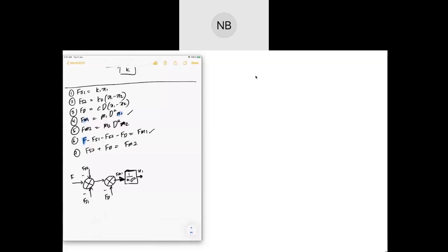So for equation number 2, you look here. This is a variable, this is a variable, this is a variable. All right. So in this case, those are your input and output. The only thing that you have is K2 as your parameter. So when you have K2 as your parameter, you need to decide now, X1 is your input, all right? But you see here, X1 has a minus, isn't it? So when you have a minus, you need to put a summing point.